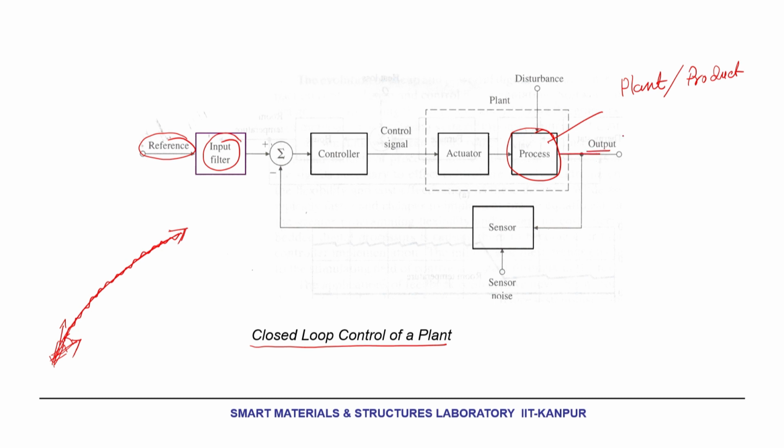These outputs I am measuring through a sensor, and then that output data through the sensor is coming back and fed in at this point. And you also have a desired trajectory. So, for example, as I told you, at a particular point you know that you have to go tangential to this line, and the sensor tells you that you are heading this way.